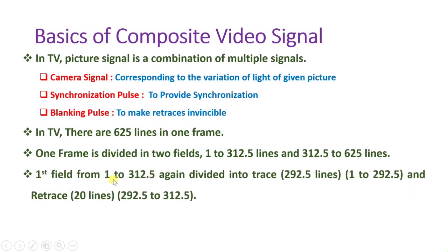Alignment polarity in composite video signals. Video signals can have two polarities: 1. Positive alignment polarity with alignment pulses facing upwards as in Figure 7.2. 2. Negative alignment polarity with the alignment pulses facing downwards as in Figure 7.3. The video signals shown in Figures 7.2 and 7.3 both contain the same image information.